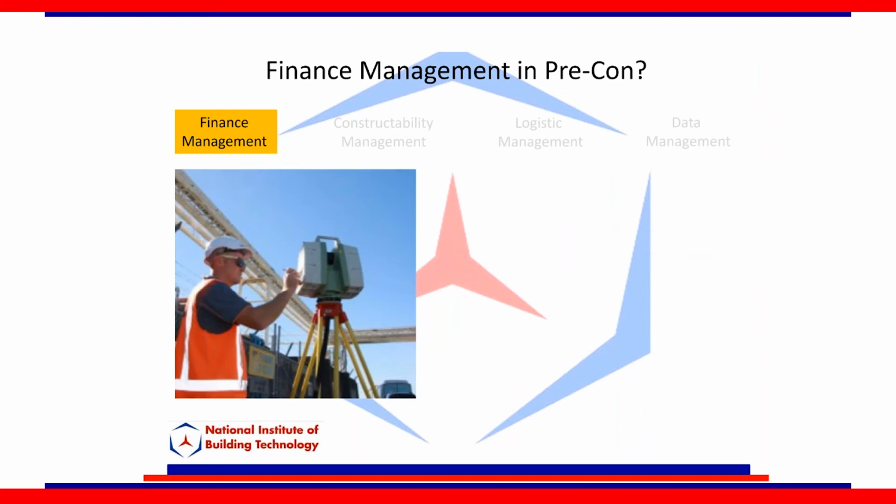Laser scanning is becoming a huge tool. I used to see one project of 100 that was getting scanned. Now I see 15, 20 projects out of the 100 that get scanned. The point of scanning is basically to look at as-built analysis, right? If it's a brand new building, of course, no problem. But if you're retrofitting something, tearing something down and renovating, it's important to understand what is there to the nth inch.